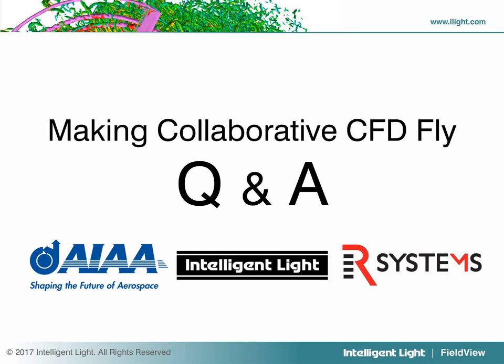Okay, thank you, Nathan. Here's another question. Is it possible to difference pairs of the solutions or compute a mean or RMS of multiple solutions? Earl, do you want to take that one? Yeah, that can be done within the XDB workflow. One thing one would do is create different slices, and then on those slices, you can map all the different solutions to that same slice, and then do differences and means and additions, things like that. That's very, very doable. I've actually done that with different projects.